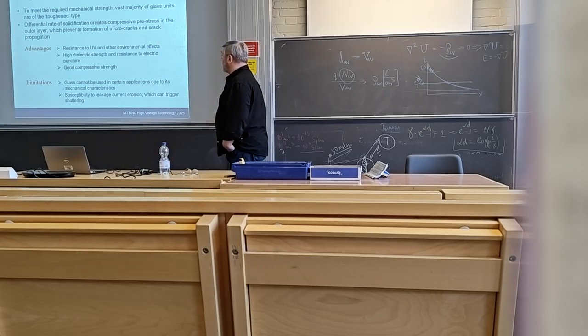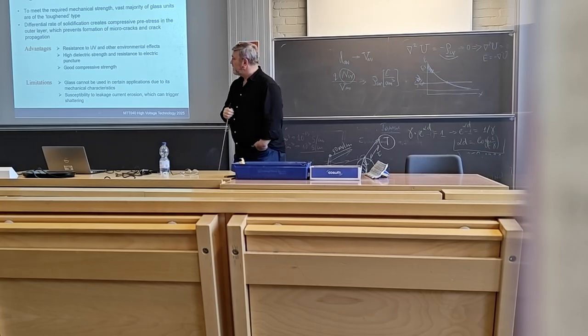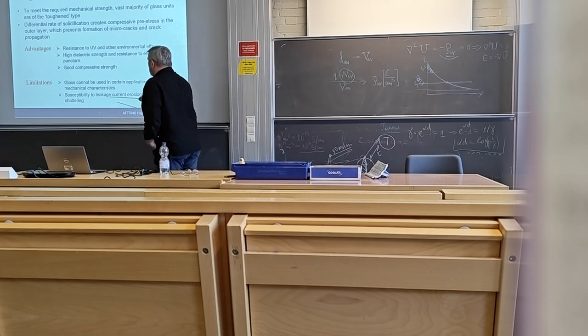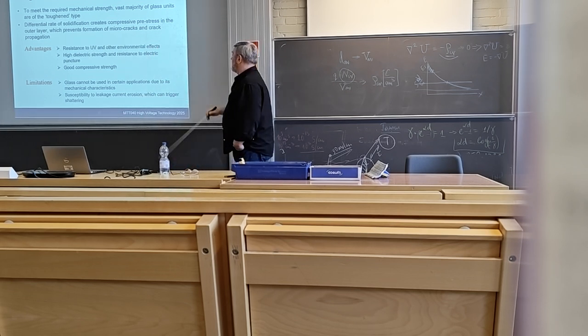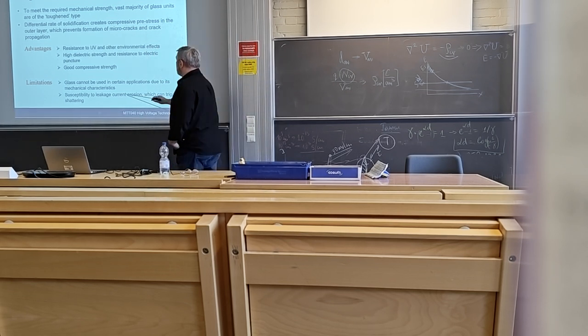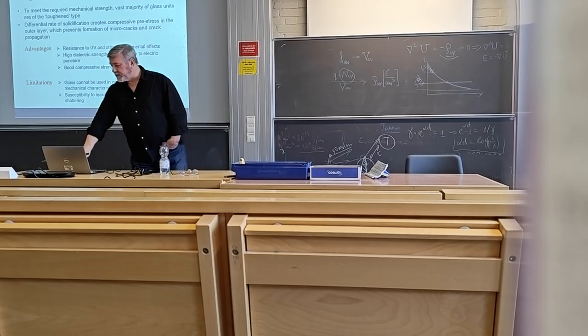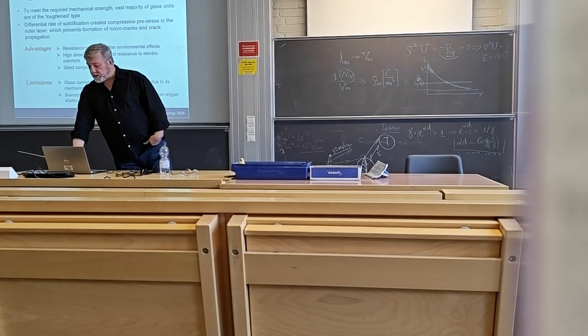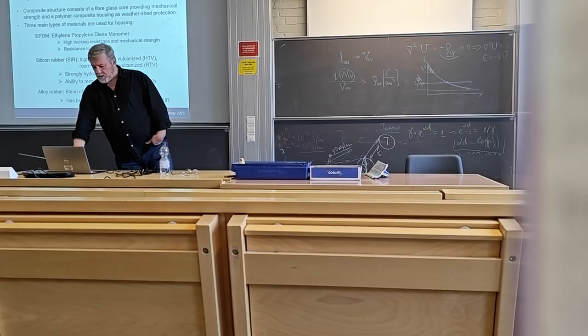Glass cannot be used in certain application due to mechanical characteristics, yes. When there is a vibration or something, this prestressed condition may lead to cracking simply. Yeah, leakage current erosion, that's what happens on the surfaces. It creates then conducting paths.